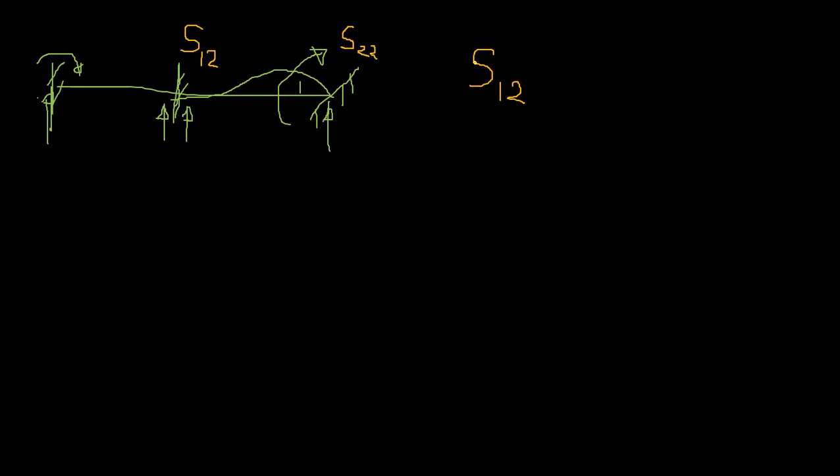So that is stiffness S, right? So there will be induced bending moment only in this part, not in this part. Why? It is 0, right? This support is not rotated. This part is not affected. This remains as it is, right? So if it is 1 here for EI over L, here should be 2EI over L.